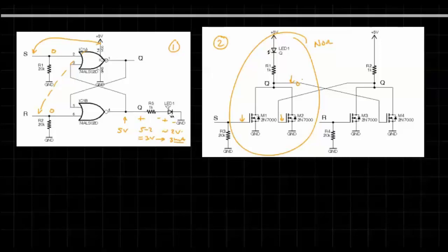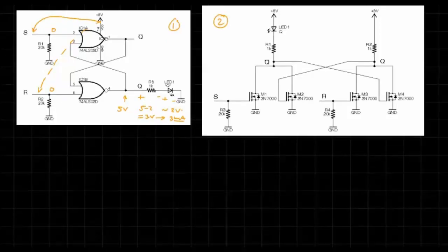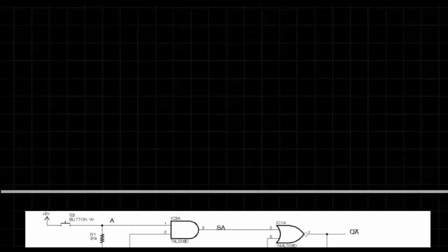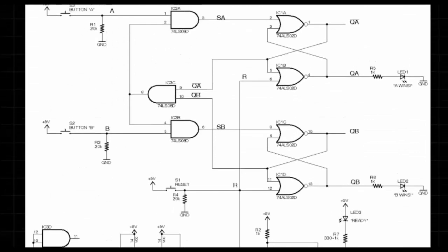So that's a NOT function, a NORing function. So you're going to build that circuit, which will function just like the NOR gate implemented one on the left, and also just give you some practice using MOSFETs. The main circuit you're going to build is this Jeopardy switch, okay?